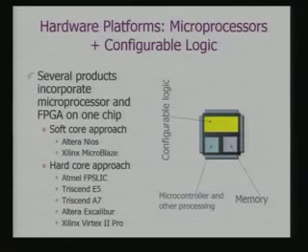In fact, with this background, let's look at some of the existing platforms on which these kinds of strategies can be used and applied. There are a number of these kinds of hardware platforms which are available today, where you have microprocessors and configurable logic. The ARM example was the ARM integrator board with a separate FPGA board. Now, we are talking about maybe a single device which can have microprocessors as well as the configurable logic. In fact, there are two kinds of devices which you get.